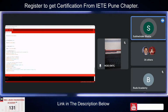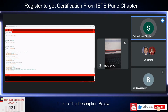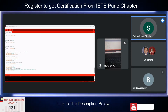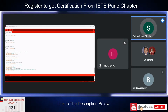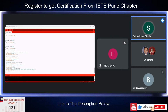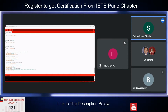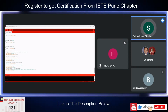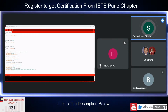And the IP address of this CC3100 board is now 192.168.1.11. Okay, this will get. And signal strength is -77 dBm. Now, to see this page in action, open a browser. It is saying open a browser to HTTP 192.168.1.11. So I'll take this.